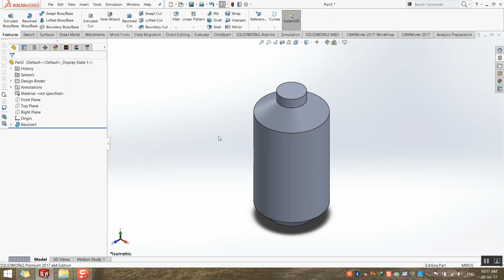Okay. As we said yesterday, all commands have been divided into two lines: extrude, cut. Okay. So you have another line here. This means that these commands are not for extrude, not for cut. For what? For modification on your model. Meaning, if you need to add a fillet, or a chamfer, or make a shell. Okay. Now this bottle, we need to add some fillets here to be smooth.